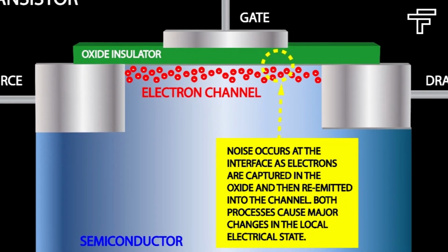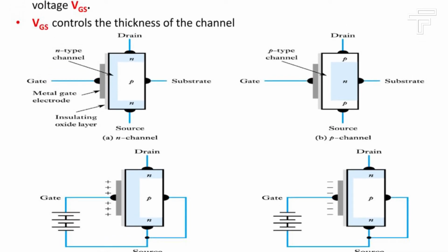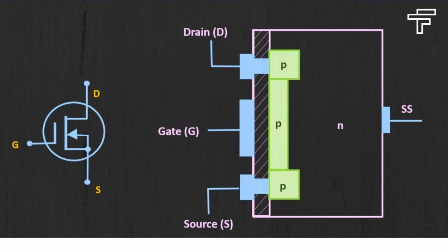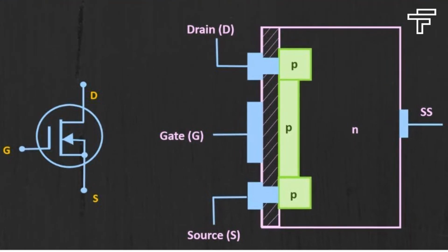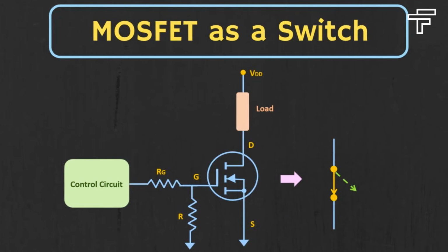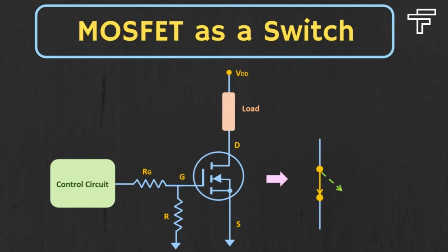Similarly, oxide in the name can also be a misnomer, as different dielectric materials can be used with the aim of obtaining strong channels with smaller applied voltages. The depletion mode MOSFET, which is less common than the enhancement mode types, is normally switched on, conducting, without the application of a gate bias voltage. That is, the channel conducts when V is equal to 0, making it a normally closed device.